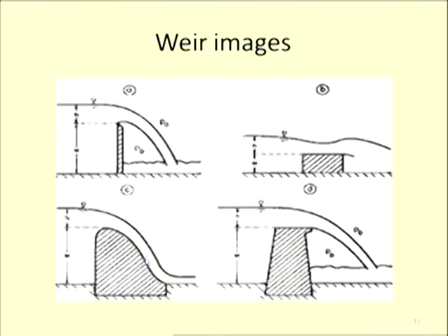In dam engineering we call it an ogee shape. Generally it is constructed for spilling water, in spillways, where excess water is allowed to flow downstream, and in weirs also this kind of structure can be used to measure the flow. And here this is a broad-crested weir with a notch provided at the end so that water is not touching the downstream side here,